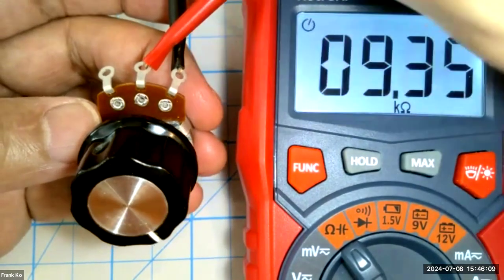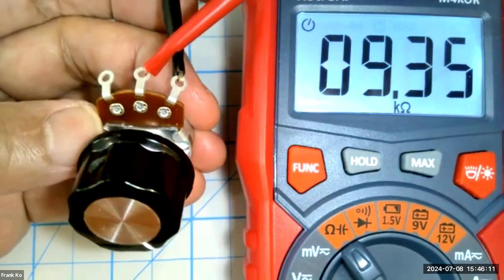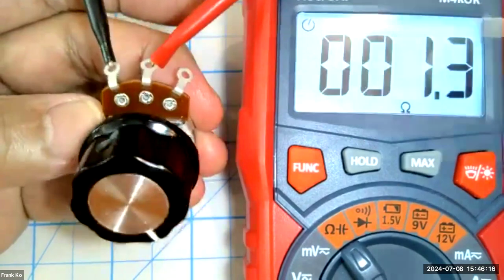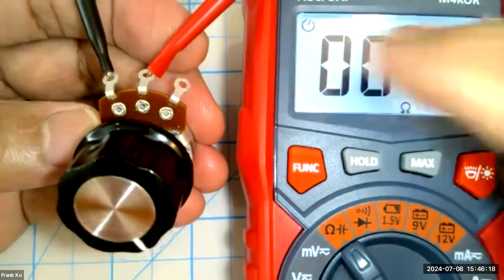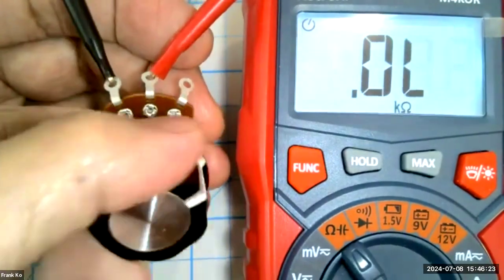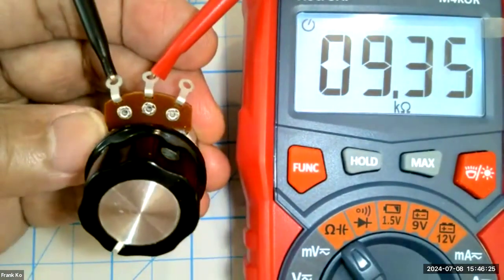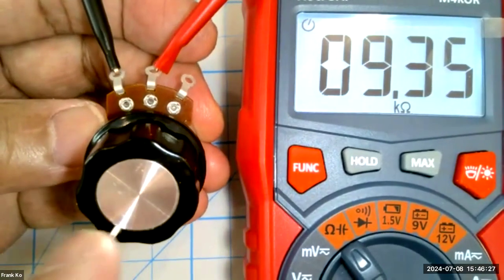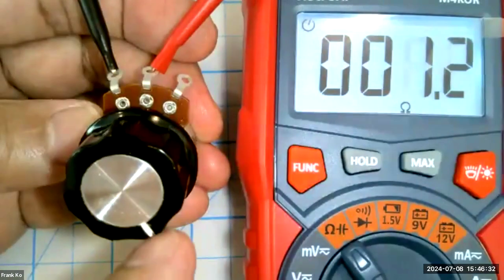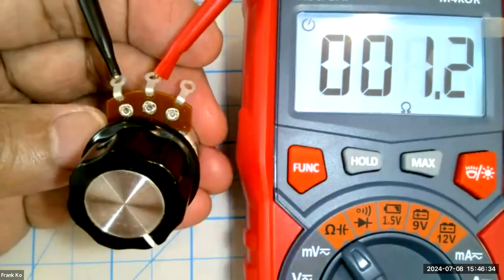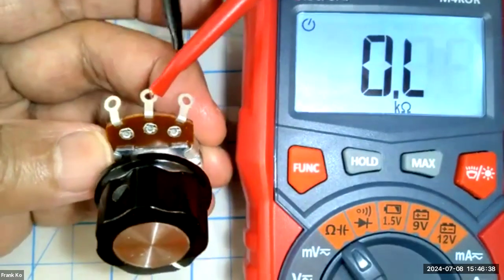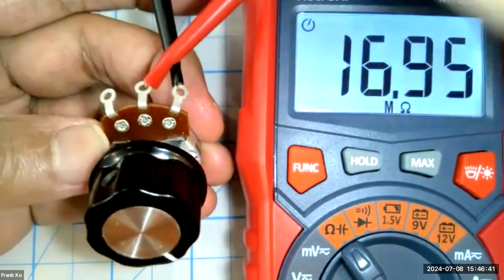So when you go to use this potentiometer in your breadboards or in your projects, if you were to make a connection between one of the inside pins and one of the outside pins, and you rotate your knob in a counterclockwise fashion to what is traditionally a minimum, and it shows a maximum, whereas you rotate all the way over to the far right-hand side and it shows a minimum, all you have to do is switch your connection from one outside pin to the other outside pin.